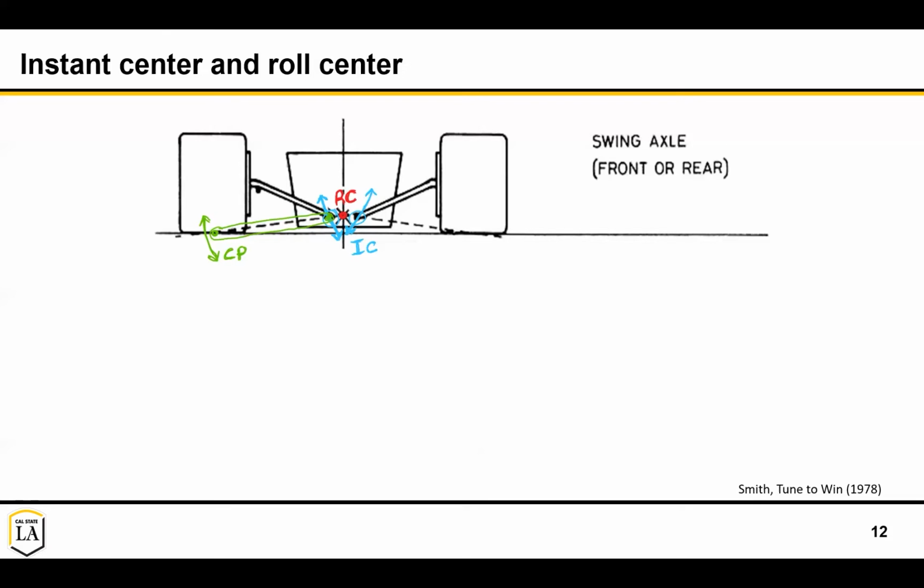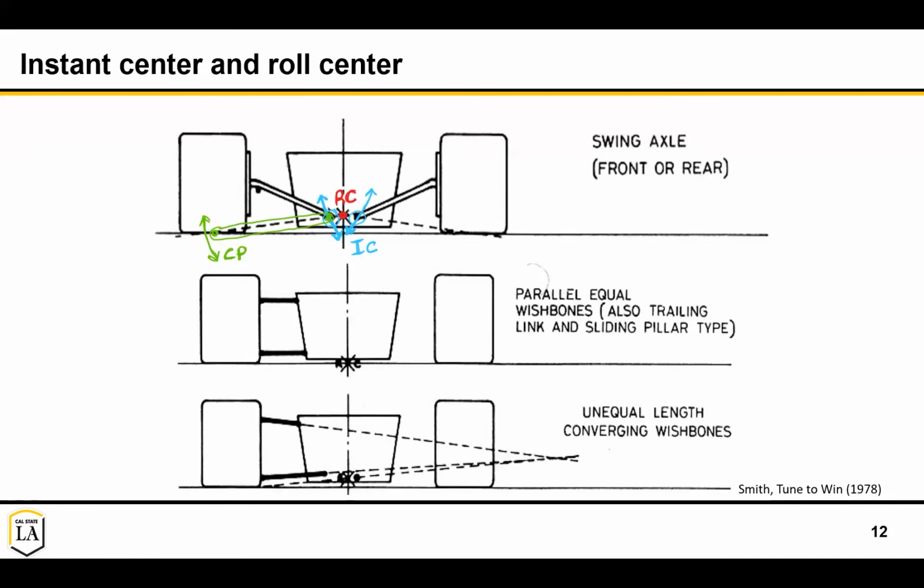A couple other things to keep in mind is that the roll center should typically travel with the CG in the heave modes so that your roll moment isn't changing, as that would feel awkward for the stability of the driver. There's already so many things changing dynamically through the turn that you want to minimize the number of things that are changing. In addition, as the suspension travels up and down, you don't necessarily want the tires to decrease in track width, as that would cause them to scrub across the ground, which could hurt your traction. But most of us aren't running swing axles.